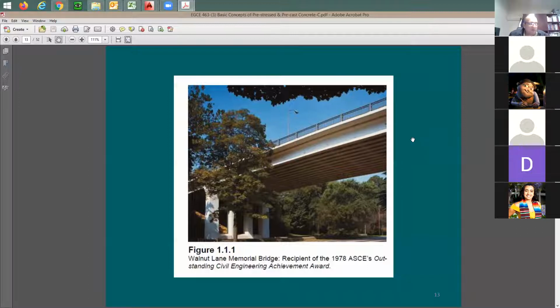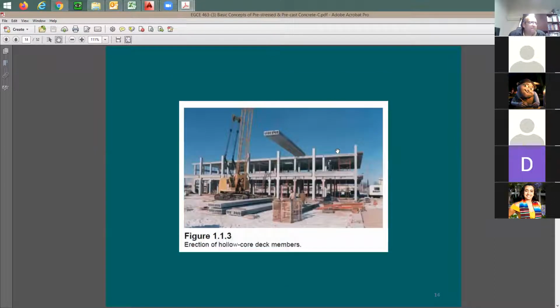They put it on a big truck. I'm sure that you may have seen it already. And then they start to install it. So it looks like steel construction, but actually it's made out of concrete. It's a different product, right? You just put it in place. So you don't really need to close this roadway for a month because you want to pour the concrete. This is going to be closed for only maybe 2-3 days, maybe the same day they can be done with it. And once you put this in there, now they can go on the top and start to form for the deck. The formwork itself is going to be supported by these beams, so it saves lots of time and hours.